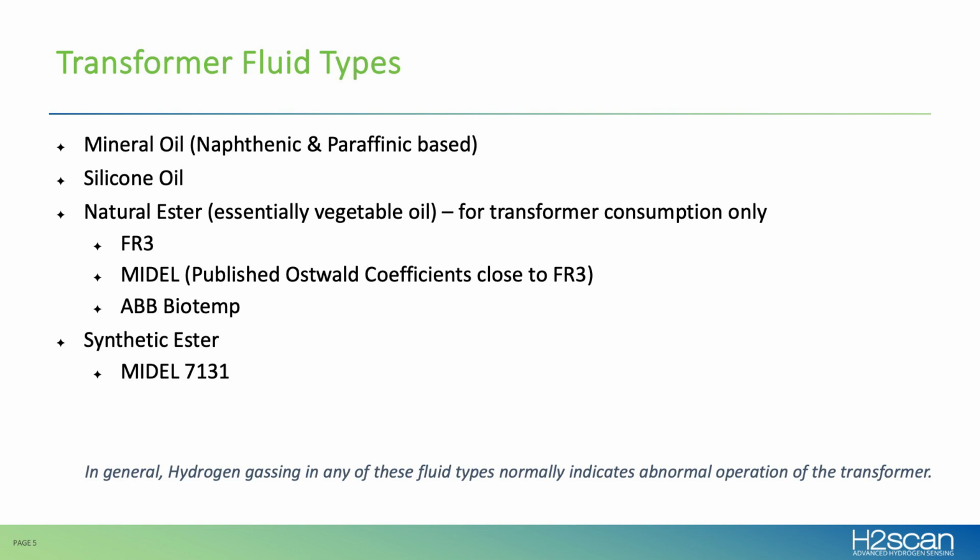And it is important that when you look at standards, most of the standards are written around mineral oil. And in some cases, the gassing behavior of these other fluids is very similar to mineral oil. And in some cases, there's some strange things like stray gassing that can happen. Even if there isn't a fault, your fluids can generate gas just if they're introduced to ambient air with oxygen. So these are all various behaviors that you really should look into and work with your manufacturer of those fluids to understand the gassing behaviors of that particular fluid.